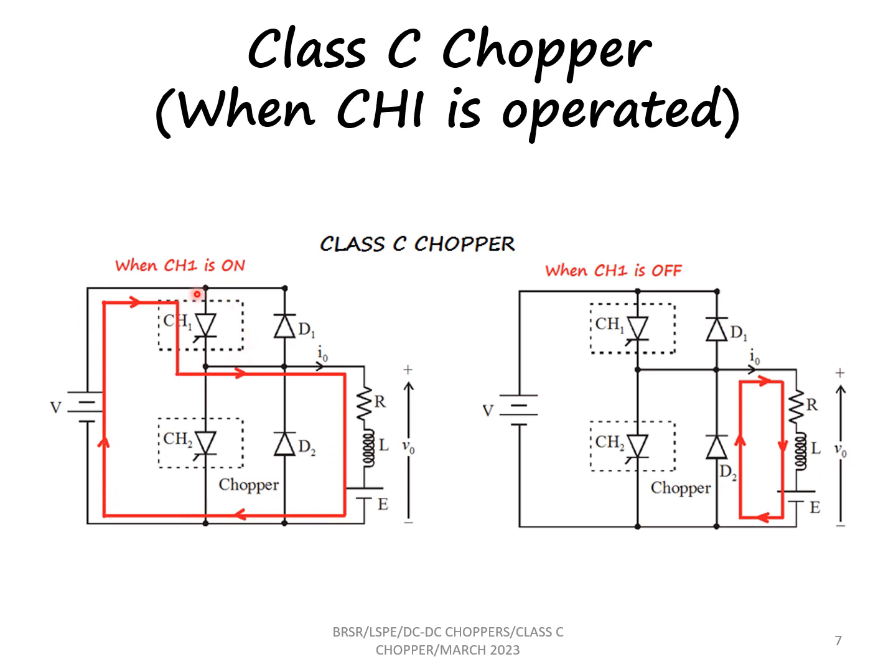When the chopper is off, the current flow in the load is because of the freewheeling diode. If we see the voltage, output voltage is going to be positive and the current flow is also positive. So this leads to the first quadrant operation. This is similar to a class A chopper operation, and here the motoring action can be conducted for a load.